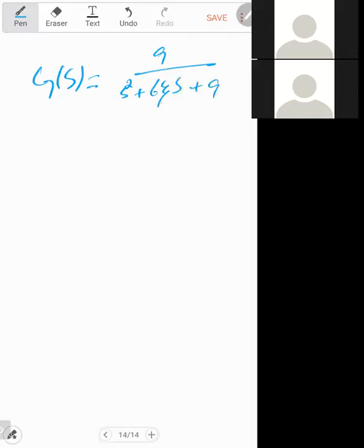And let's say that zeta is increasing, meaning in the previous case we had zeta equal to 1.5, so we can say zeta is equal to 2, 3, 4, and so on. So if zeta is increasing, let's see what the unit step response of this system is. This is y of t, and this is t. Unit step response means the input is the unit step function.